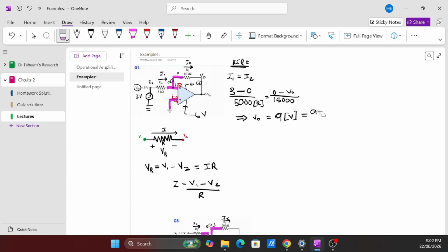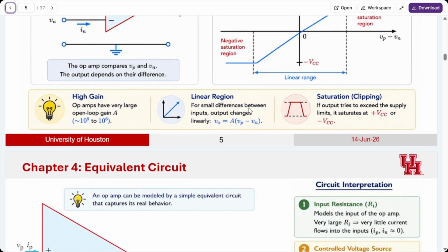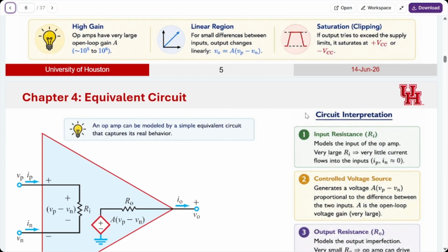It's always going to be 6 volts, regardless of how big your input supply is, or how small your input resistor is. It's always going to be 6 volts. It's going to be stuck at 6 volts, and the graph is simply just going to look like this. You have a negative 6 volts here, and if your input is going to be negative infinity, it's just going to be stuck at whatever linear limit it has, right? Yeah, it's called saturation.